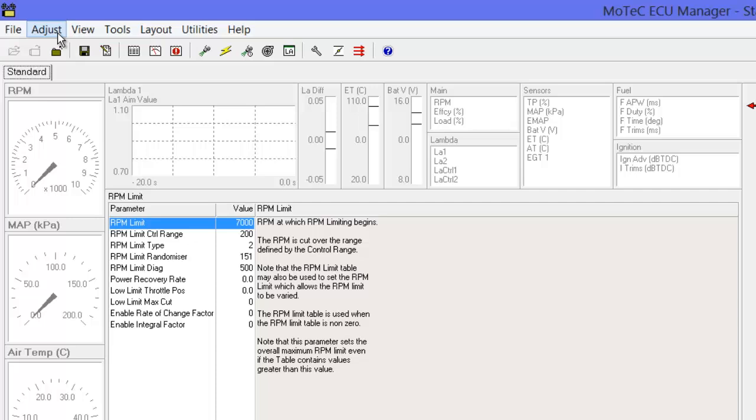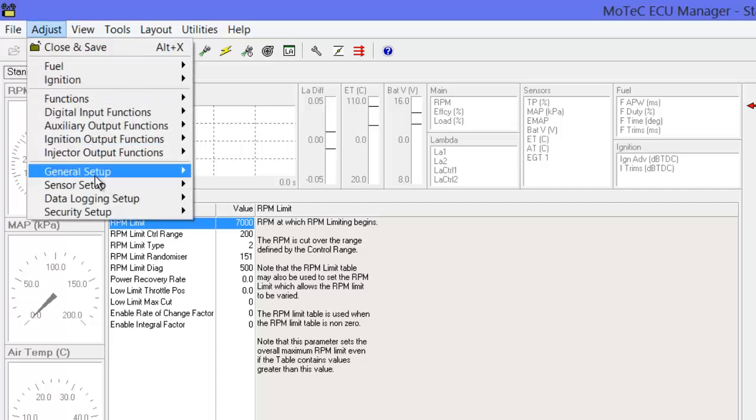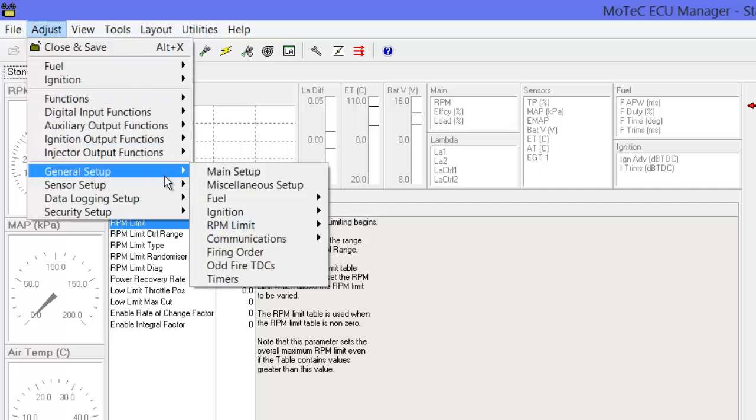The way the M150 deals with the injector setup is quite advanced and still not too common, so we're going to look at the settings in a more conventional Motec 100 series ECU. In the 100 series, the injector operation mode is defined partially by the trigger mode the engine uses. Where possible, we want to use sequential injection, where each injector is operated separately, and this requires that the ECU has a sync input to tell it where in the engine cycle it is.